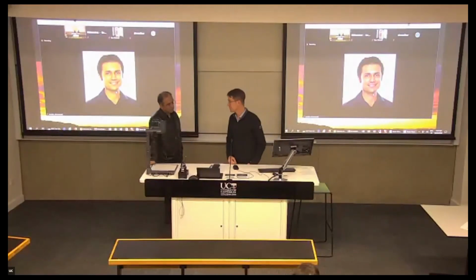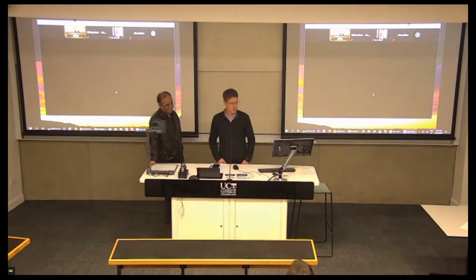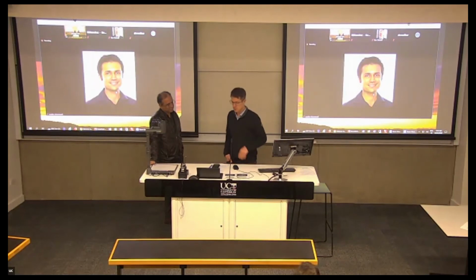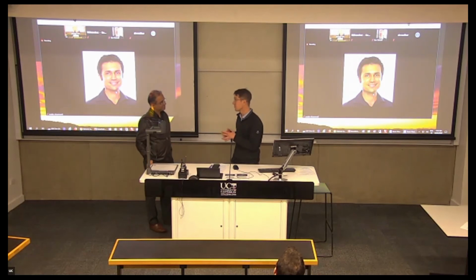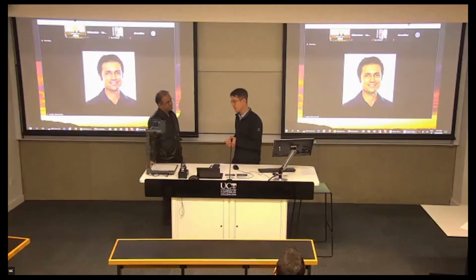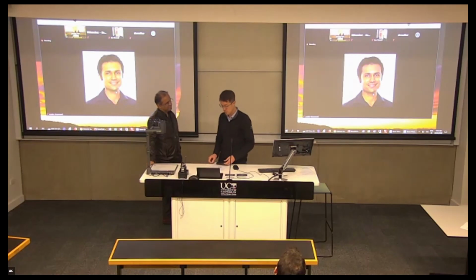Well, I'll open up with a comment and question. I thought it was a really interesting talk, and you identified a few areas for research. One question I have around the lumped plasticity approach is, with the elongation captured now with lumped plasticity, what does this mean for our diaphragm modelling? Because most of the time when we do time history analyses, we assume a rigid diaphragm, but I presume that's not going to work very well. Have there been solutions around that?